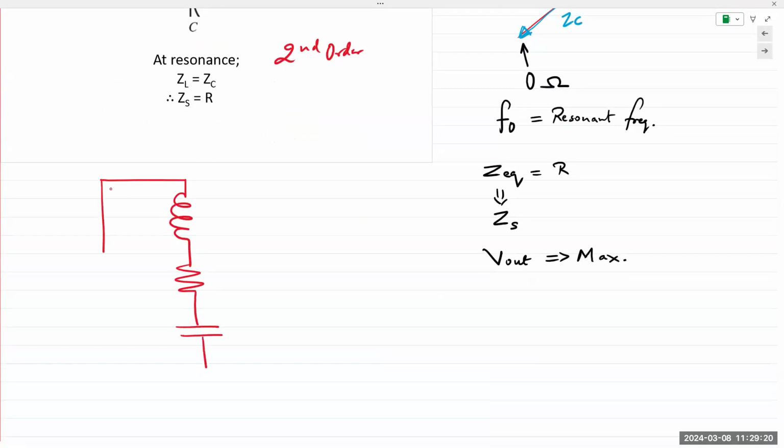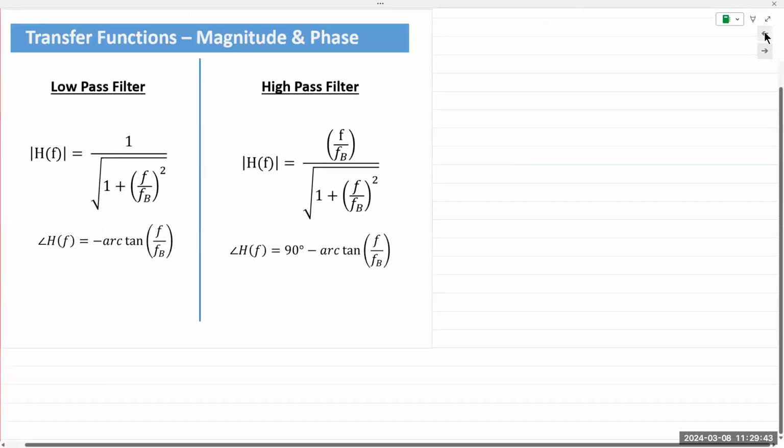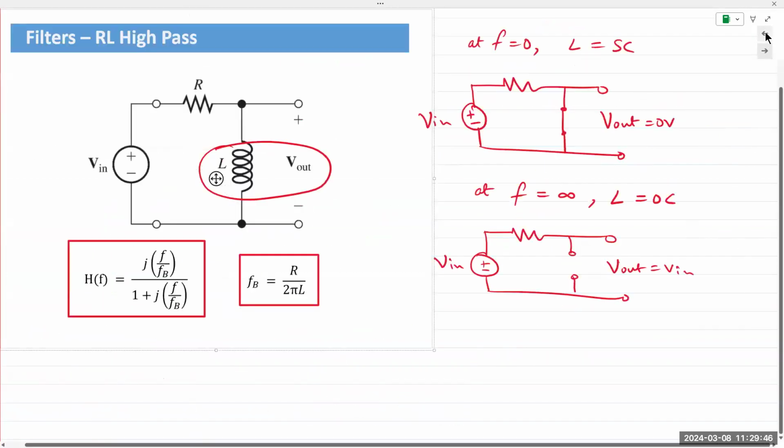If you remember from last class, I drew a similar circuit for the RL and RC. Our output is being taken across the resistor. What if the inductor was no longer present in the circuit? What kind of circuit would we have? It would be RC, and because the output is across the resistor, what kind of filter?